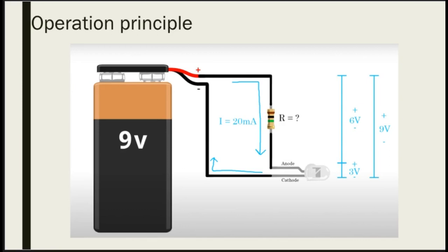The other thing as well is, do you remember what the last band is called? Again, you never read the last band first, because the last band is either one color or another. Only 2 colors are permitted for the last band, Mumiza. Gold or silver. And what does it tell you about the manufacturing of the resistor?